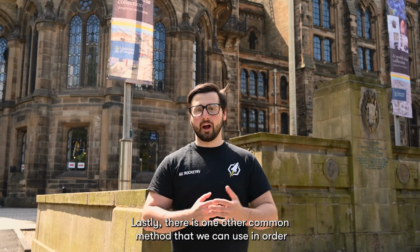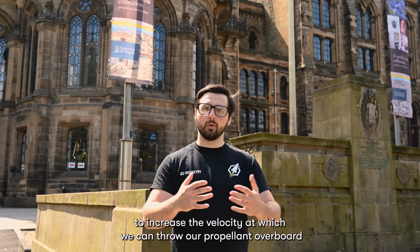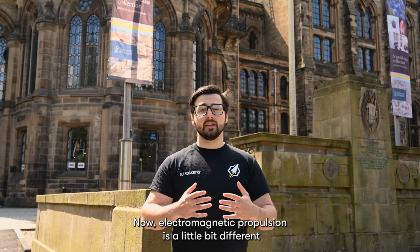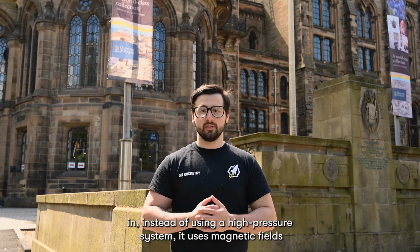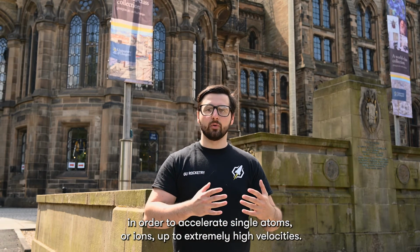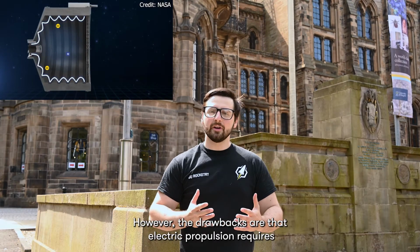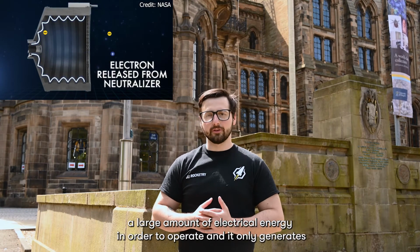Lastly, there's one other common method that we can use in order to increase the velocity at which we can throw our propellant overboard. And that's through the use of electric propulsion. Now, electromagnetic propulsion is a little bit different than traditional high-pressure propulsion systems. Instead of using a high-pressure system, it uses magnetic fields in order to accelerate single atoms or ions up to extremely high velocities.